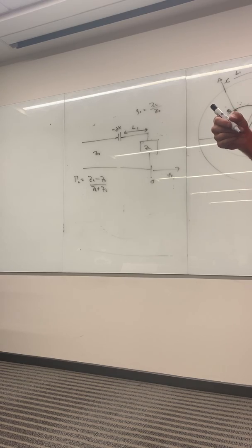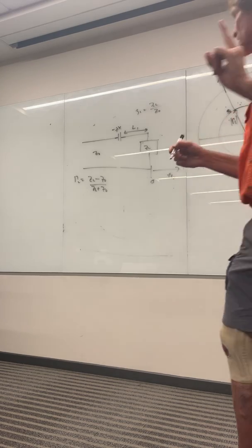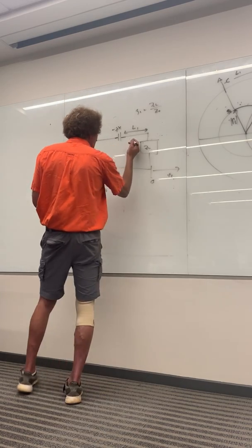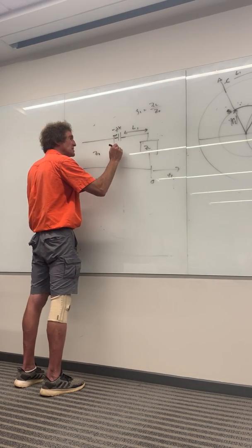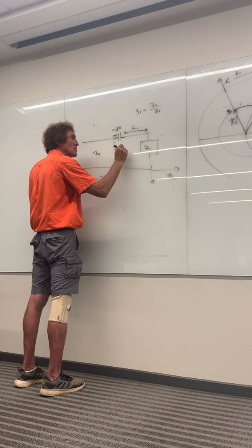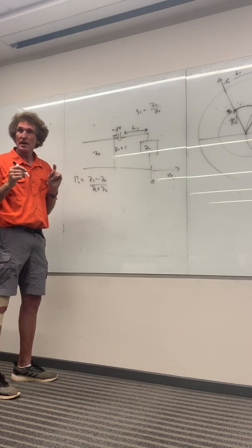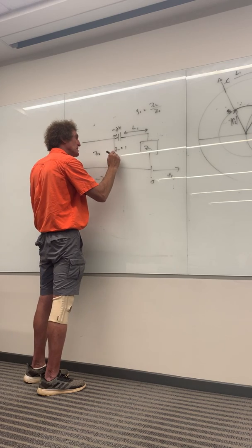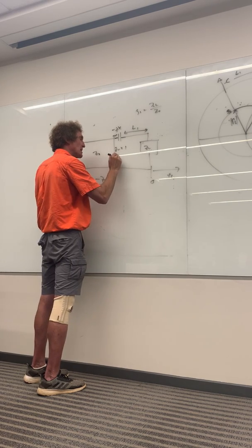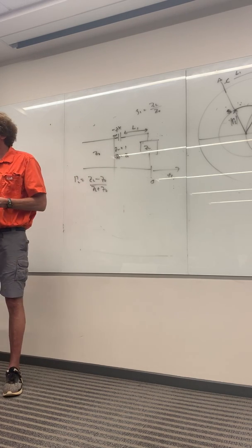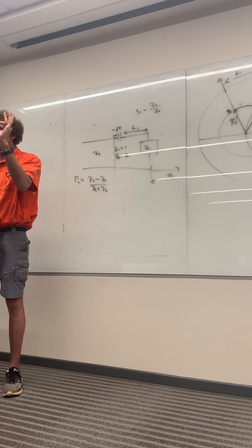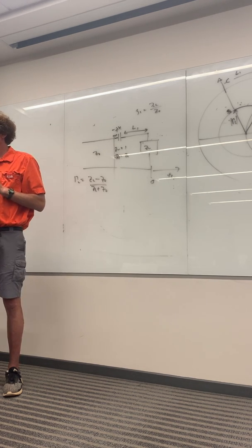Now, what would the normalized impedance be then, looking at this point, if I'm assuming it's a distance L away? Well, the normalized impedance, that would be Zn at this point, would be equal to just 1, right? And that means the actual impedance would be Z0, which means the reflection coefficient would be 0. Then the input impedance would be the characteristic impedance of the line.